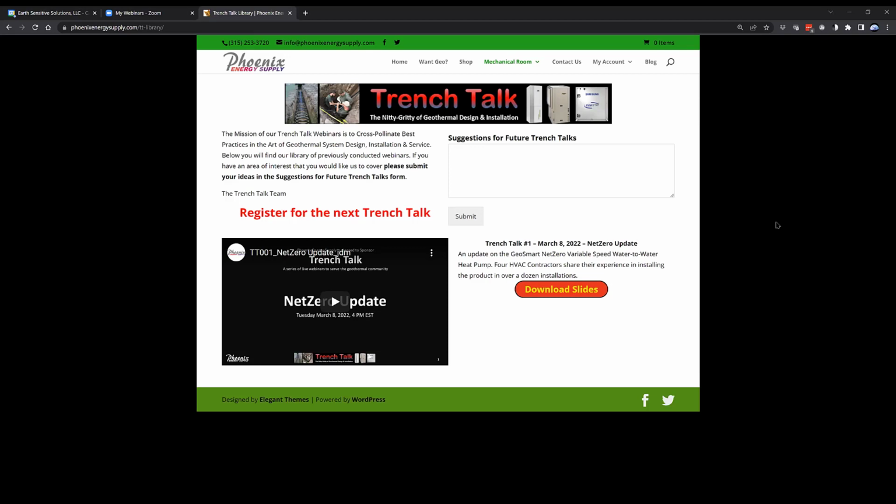Okay, another question here. Rob asked that the Velo variable speed pumps with adjustable head pressure are expensive. Can you validate the monetary savings in using these pumps versus a constant speed pump? Yeah, certainly we've analyzed pump operating cost under a lot of different scenarios, and almost routinely we come up with energy savings in the 80 to 90% range when using these types of pumps. ECM variable speed pumps have incredible turn down.